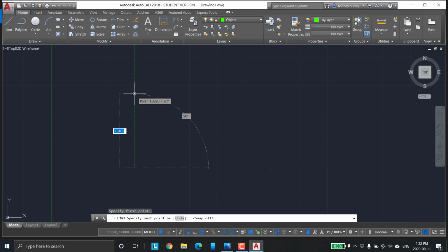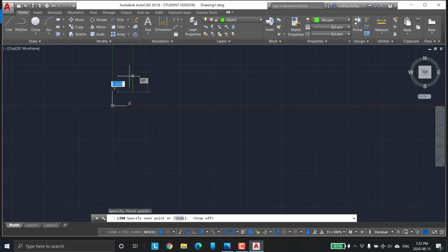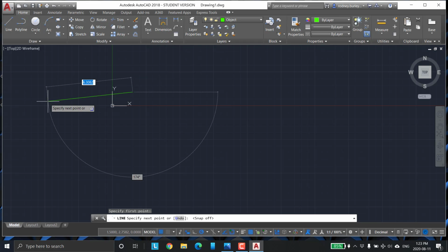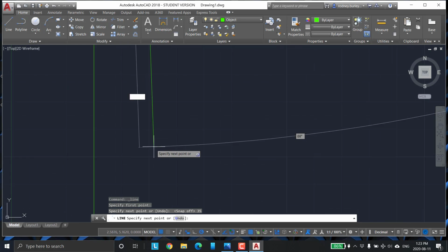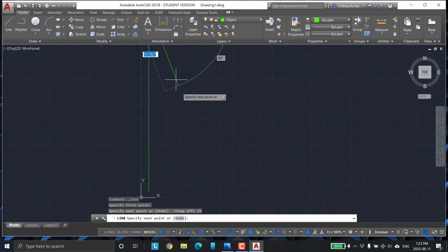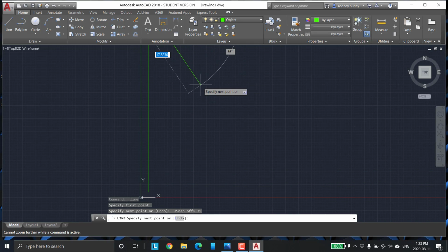Now I can drag this up to my right height, or I can just type the value in. You notice I'm facing upwards, and it's locked up, so it's not on an angle, it's locked straight up. For the dimension, let's see what the dimension was. It was 10 and 25, so I want to type in 35, enter. And now it's gone off the screen. Hold the middle mouse button down and drag it down, and at the same time zoom out, and we'll get the whole thing in.